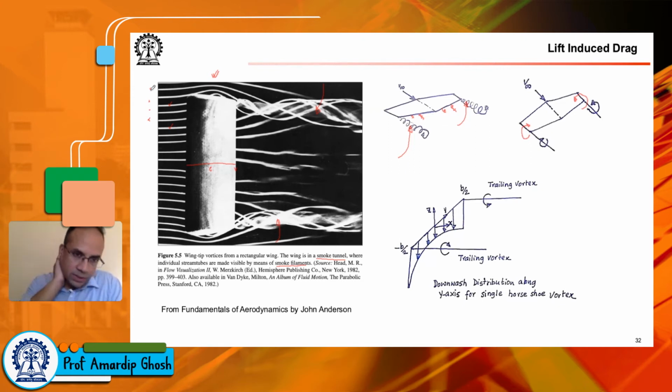If you are running these tests in water, you can use a colored dye. So you will have a tube with holes, and through that tube you can inject some colored dye at these different locations, and you can get a similar visualization. In NAL, actually, I saw these. Well, of course, I had read about it, but for the first time, I saw flow over a delta wing being rendered visible using colored dye in water.